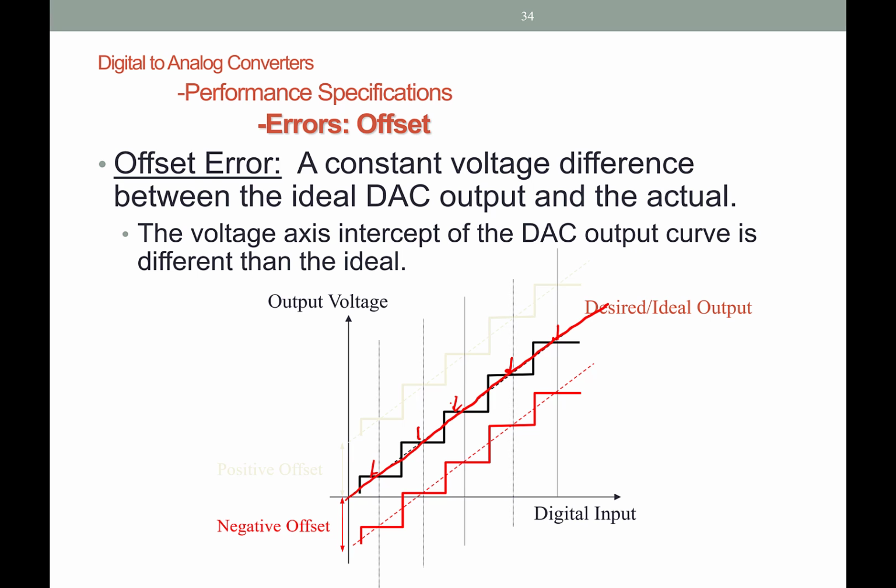So we can have a negative offset voltage, so everything would look okay, but it's offset in the negative fashion, or it's offset in the positive fashion. So we're just basically saying, okay, we've taken a number that typically we would think is between 0 and Vref, but now it may be between V1 to Vref plus V1, and that V1 could be a positive or a negative value to allow this sort of offset.